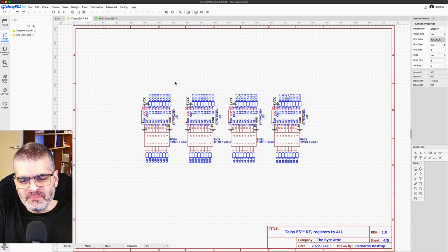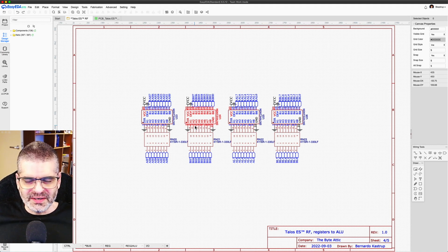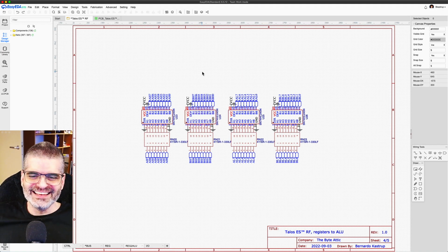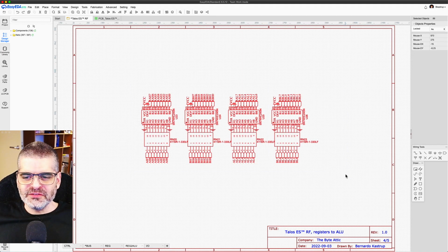And to be honest with you, the only way to really know for sure whether it's better to put the resistors right at the driver pin or somewhere else is to run a simulation, starting from Maxwell's equations for your specific circuit, which takes a lot of time, a lot of computing power, and expensive tools that require licenses, and I ain't gonna do that. I'm doing all this not even to make this computer as fast as possible.